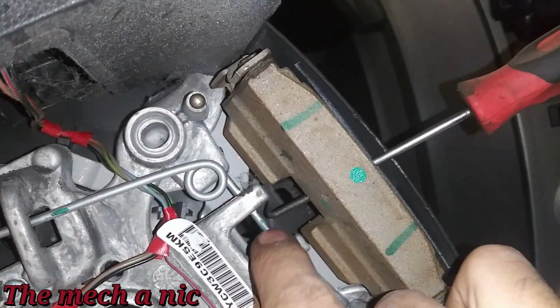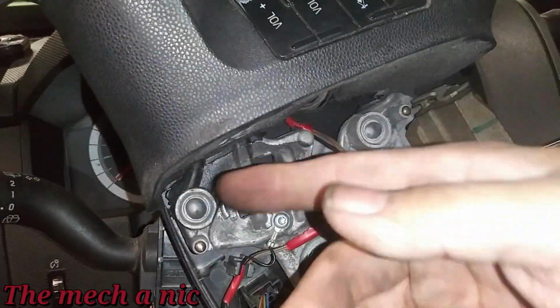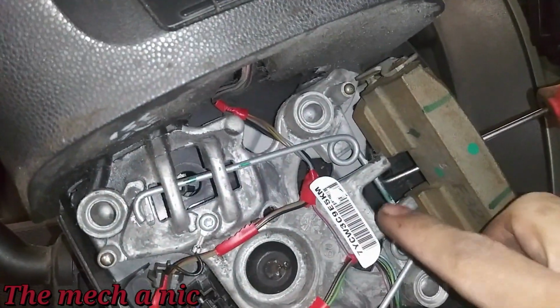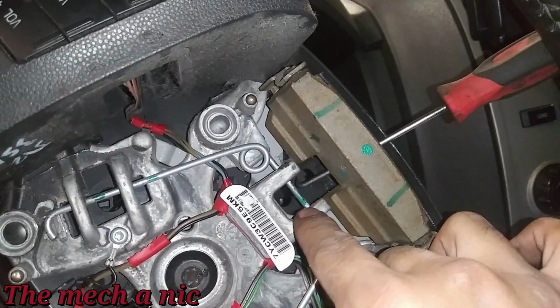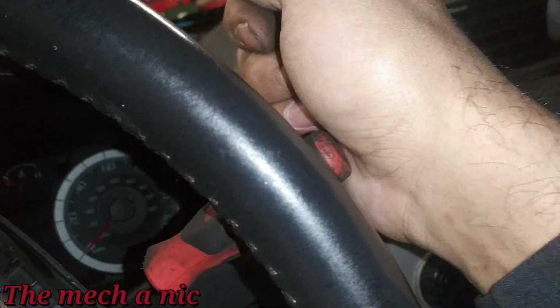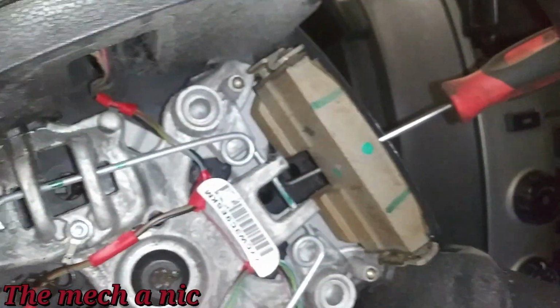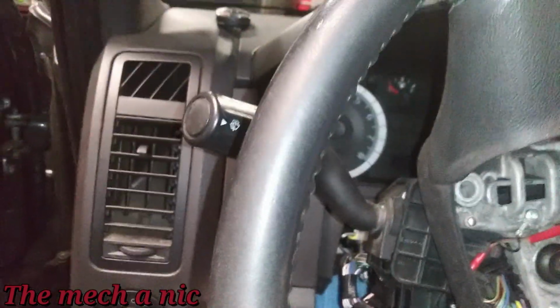Once I get it lined up and I know it's touching that spring for sure, there's going to be a lot of tension on it because you already have these two disengaged. So this one has more tension than it normally would. At that point, once I know I'm on the spring for sure, I just give my tool a little bump in my hand, boom, and this end pops out. And that's it. The whole airbag is out.